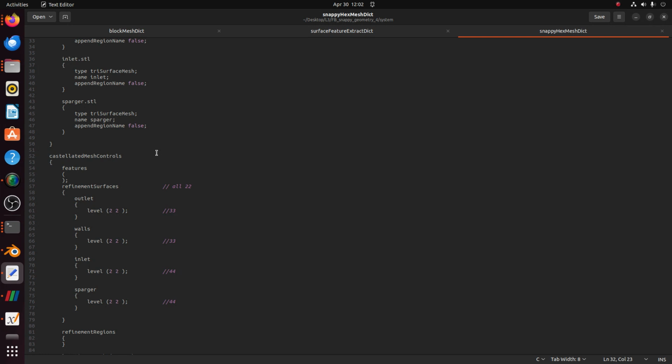Can we use block mesh? Sir, block mesh here is used for creating a prerequisite, like setting the minimum size where the geometry does not exist. So I mean, I cannot create a block mesh with this STL. That has no meaning. So we created a block mesh initially, yes, sir, a cuboid, and then used snappyHexMesh. Yes, sir. Sir, the block mesh also exists here.